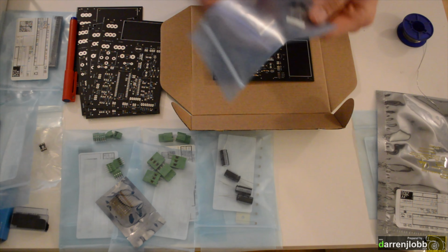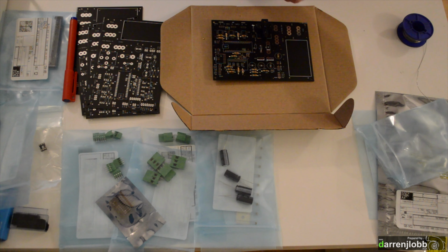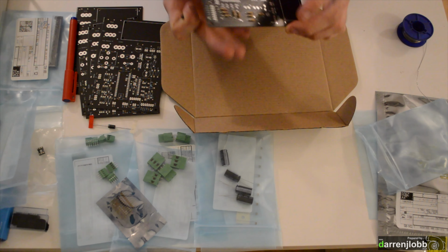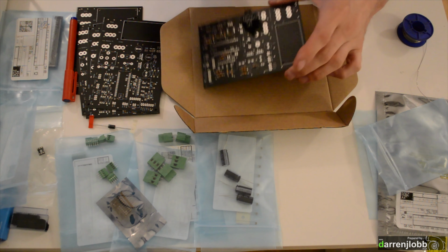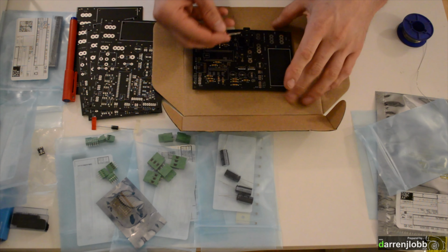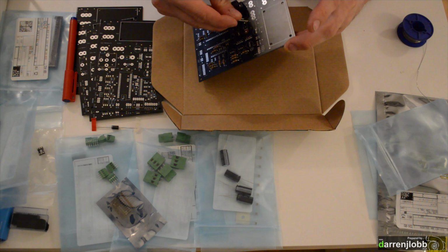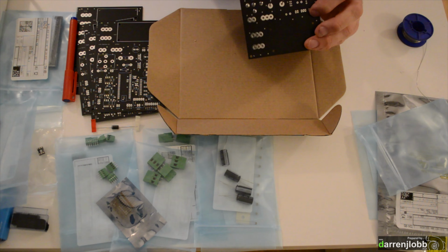Right, next we've just got one bigger 3 amp diode to fit. It's on the output side of the relay, protecting that circuit. These are a bit bigger, so that one's going to come up here on the right hand side, the bottom side on your screen. Again, it's the same thing. You've got the white strip on the diode, white strip on the board. So just put the two together, solder in like that, and solder up.